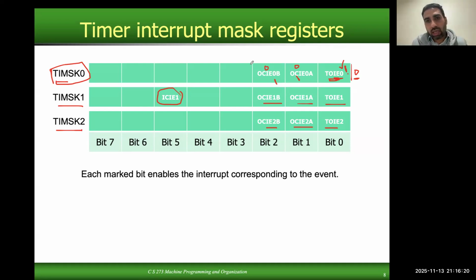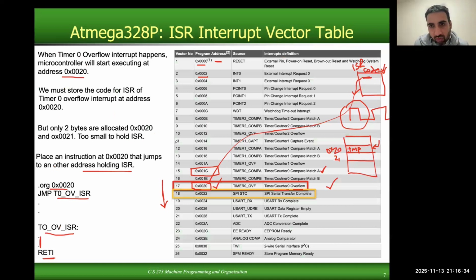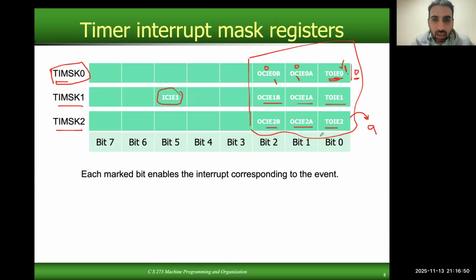If we focus only on these bits, they provide 9 different types of interrupts, right? And that's why you will see here 9 different entries in the table covering all of those interrupt types, and if you also include the capture event, it will be a 10th. Any questions? So to enable the interrupt, you need to write 1, and to disable it, you need to write 0.